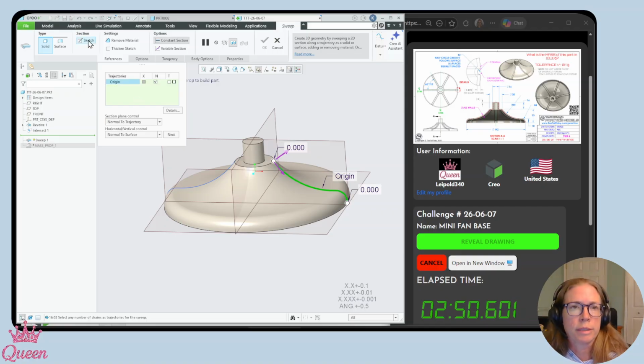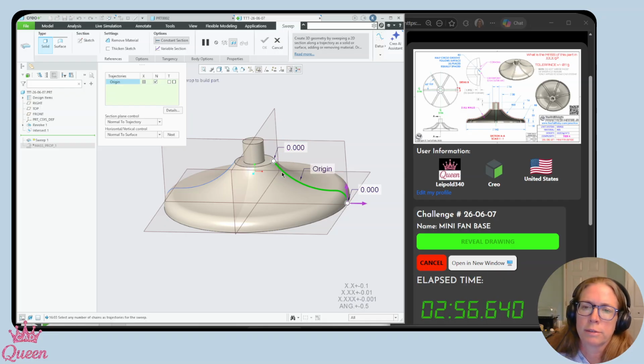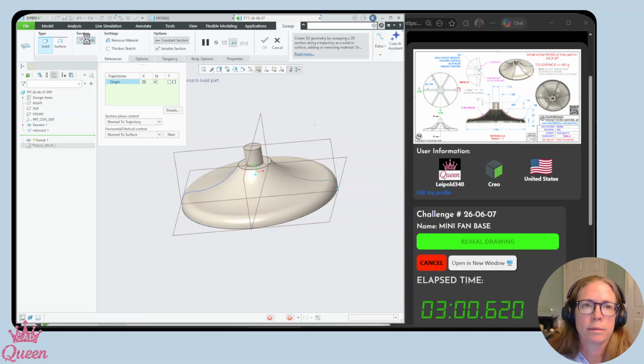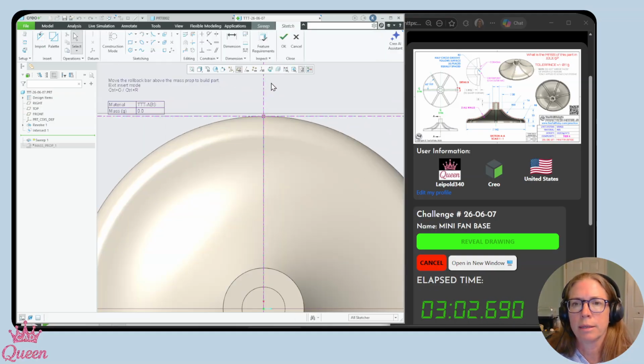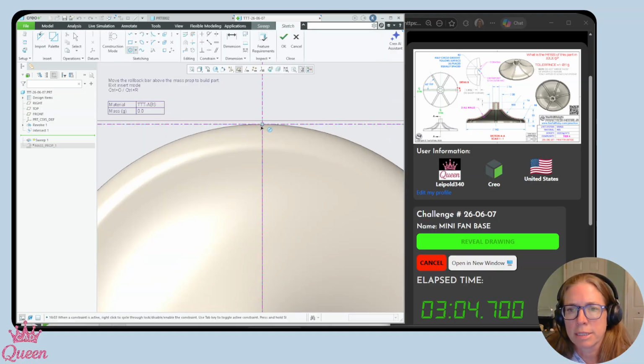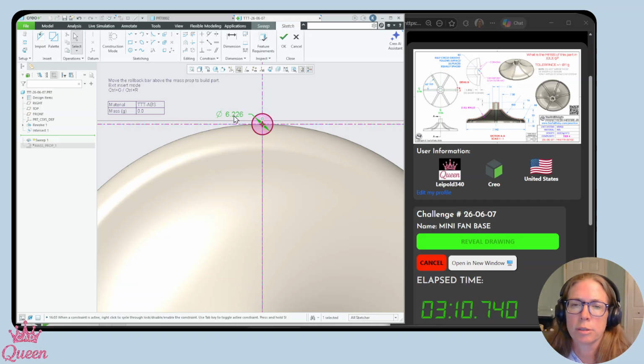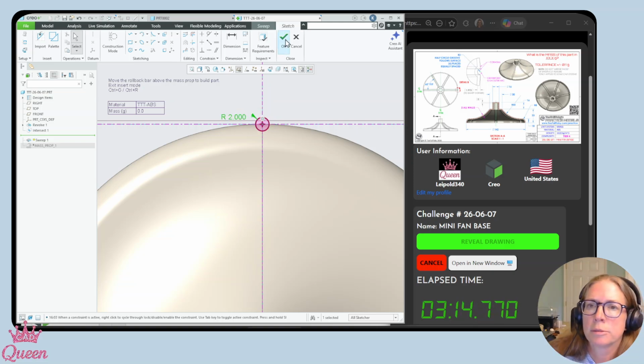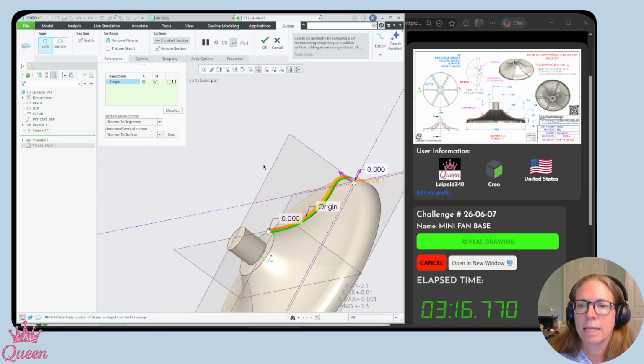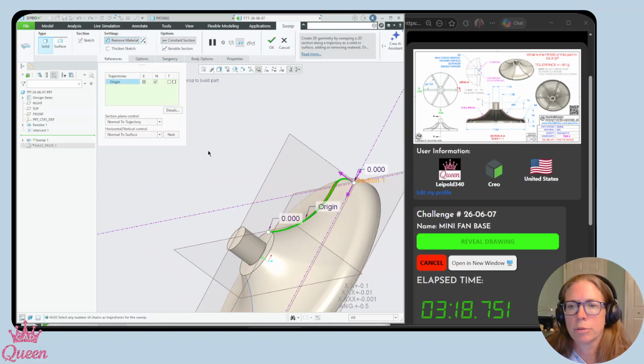So in Creo, we create the sketch inside of the sweep. I want to start down here. It makes more sense to me. So I will switch my origin to the right end and create my sketch. Okay. The cross section for the sweep is just a circle. It has a radius of 2, so I can switch this to radius and type in 2. And that is adding material, but I want to remove material.